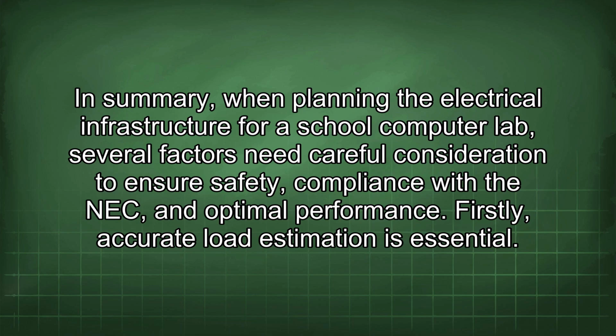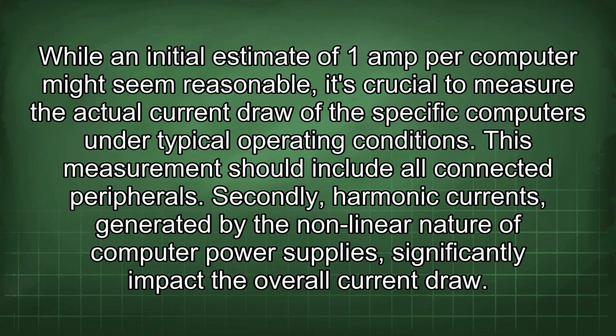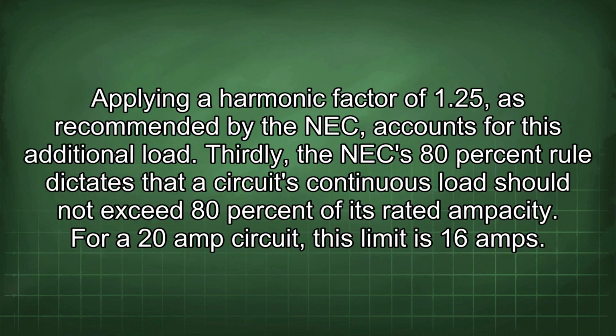Firstly, accurate load estimation is essential. While an initial estimate of 1 amp per computer might seem reasonable, it's crucial to measure the actual current draw of the specific computers under typical operating conditions. This measurement should include all connected peripherals. Secondly, harmonic currents, generated by the nonlinear nature of computer power supplies, significantly impact the overall current draw. Applying a harmonic factor of 1.25, as recommended by the NEC, accounts for this additional load.